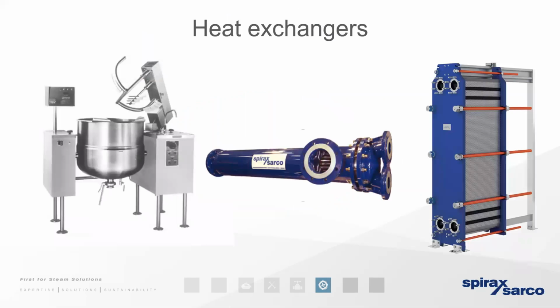So we've mentioned already, steam gives up its latent heat energy by condensing. So the byproduct of that heat exchange is that liquid condensate. So above you can see what we'd refer to as a closed loop heat exchange system. And that's where the steam goes onto the heat exchanger, it gives up its heat energy, and that liquid condensate's got to be drained away because it can't be used for heat exchange purposes.